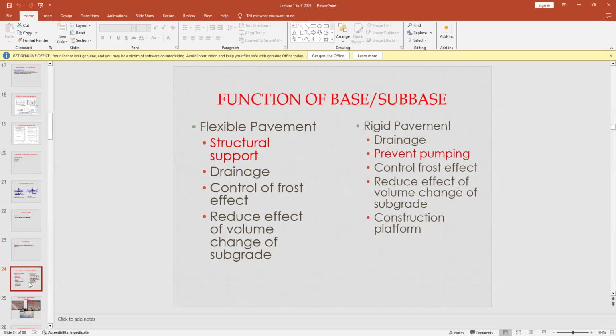The voids in the base are of such extent that they allow the water enough space to expand, and the thrust they apply in the open granular layer is much less than in a closed granular layer. Since we provide a material of our own choice, open graded aggregate, there is more control of frost action in both pavements.